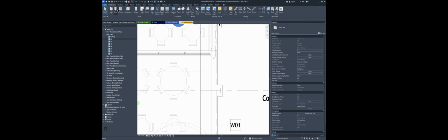And when you import it, you have a curated list of families that comes with Revit, right? Whenever you go to Architecture, Component, Load Family, usually it drops you in this folder that has these different categories. And you can pick from these categories. So there's a curated list from Autodesk.